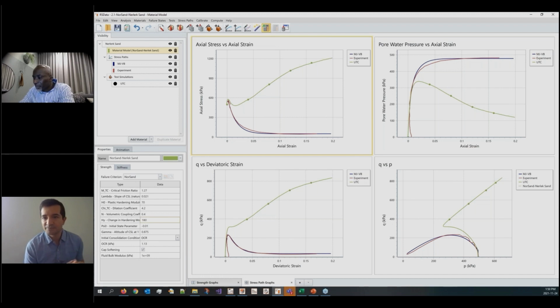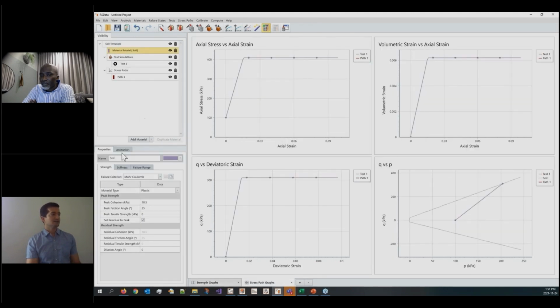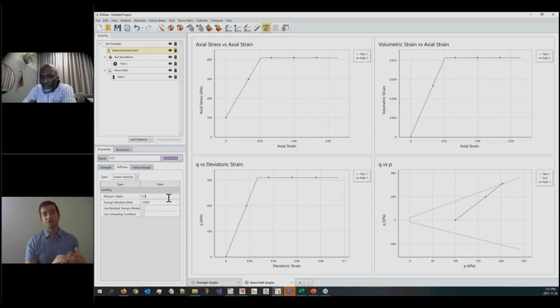Determination of elastic modulus for soil can be automatically performed by RSData. Yeah, if you have all these properties that you have in here, let me generate a new one. If you have your experiment, you can bring it into RSData. You can easily manipulate the properties that you have for a given material. Like, okay, I had the strength and the stiffness. So the stiffness, you can change as you wish and fit it to the properties that you have for the behavior that you have. The calibration that we currently have in RSData is only matching what we had in Rocscience, so it's only for strength of the material. But we will be developing a more general optimization algorithm to get you the properties and also all the parameters for the different constitutive models that we have in RSData. So we can optimize the behavior and also the strength of the material and calibrate everything here, then take it to RS2 and RS3.